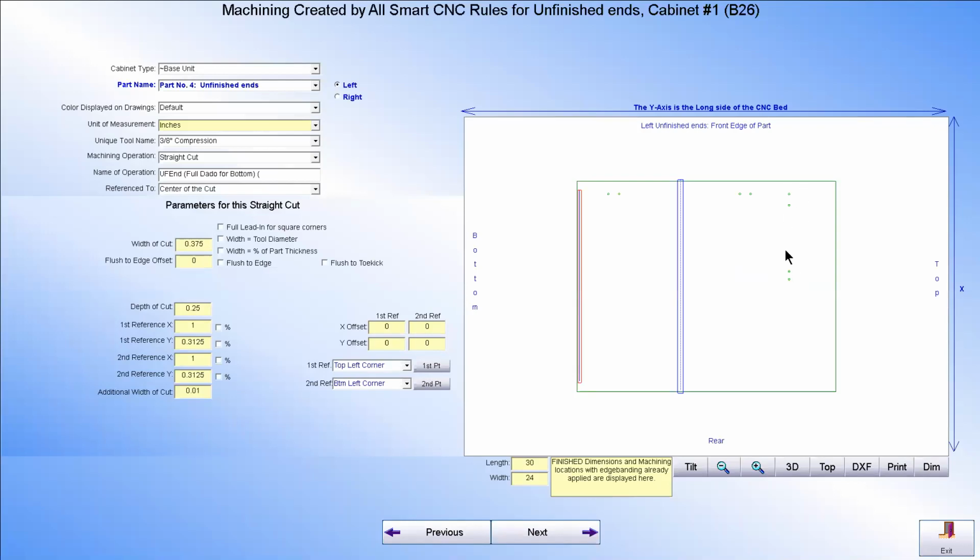I don't know if you can see that, hopefully you can. These are drawer guide holes. Here are some hinge plate holes. Here's a dado for, looks like a fixed shelf. And here's a blind dado for a bottom. Well, for right now, I'm going to change that fixed shelf into an adjustable shelf instead.